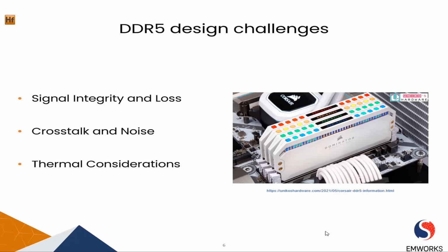Last but not least, thermal considerations. Higher data rates can lead to increased power consumption and heat generation in DDR5 memory modules. Managing thermal dissipation is crucial to prevent overheating and maintain stable operation. Thermal design considerations may include heat sinks, thermal vias, and appropriate airflow.